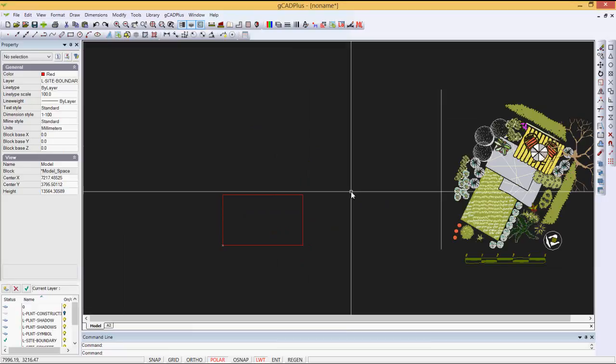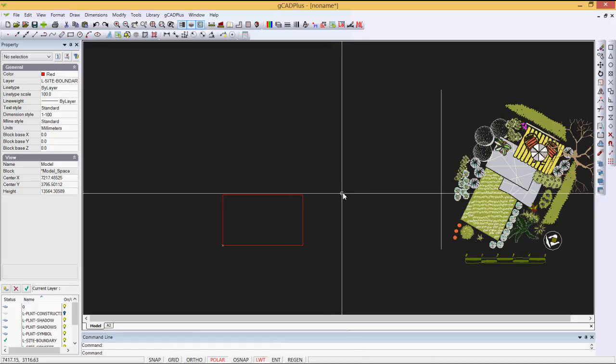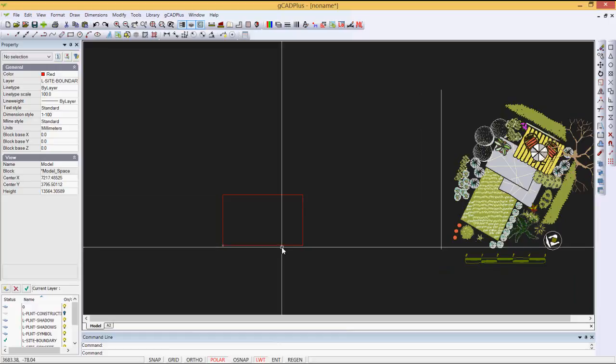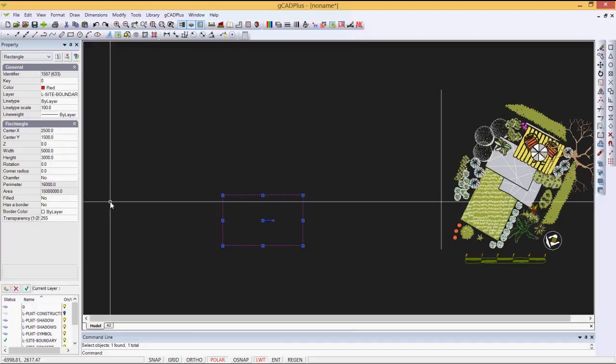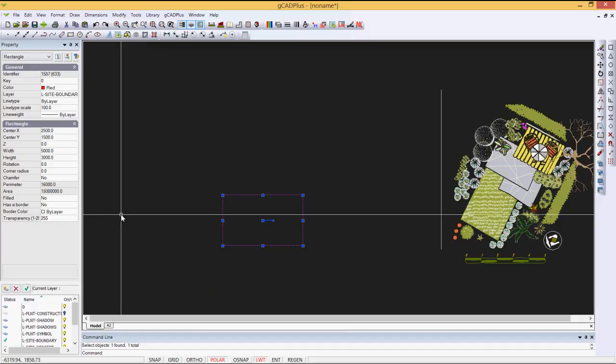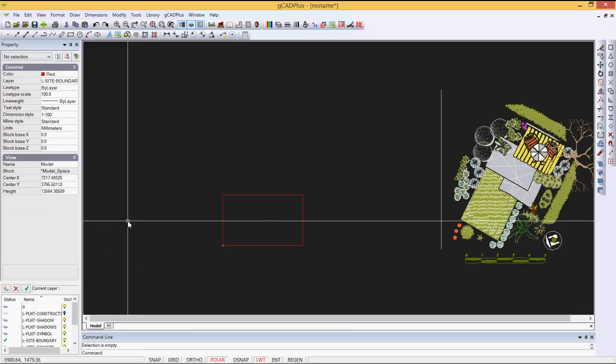So we made a lot of changes there. Once you gain experience, those sort of changes are not necessary, but for many of you this is the first exposure to computer-aided design. And why we are emphasizing these coordinate values, let's click on the rectangle now. We can read its properties. We can see it's 5 meters wide by 3 meters high. We have a value for its center point, and we can look at, is it filled or not? Does it have a color? No, it's inheriting the color of whatever layer it happens to be on.